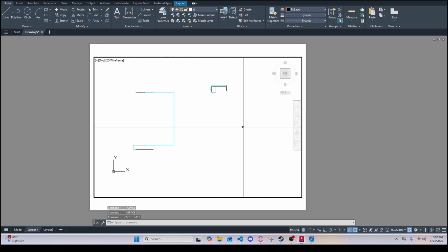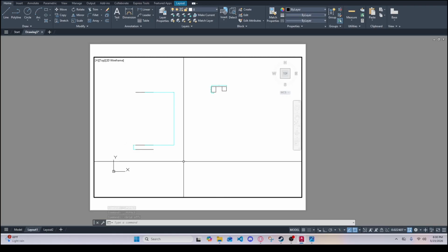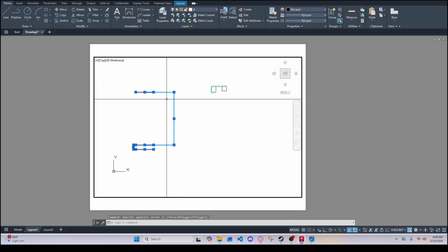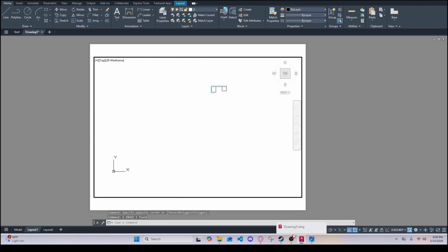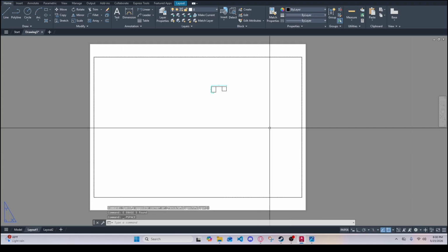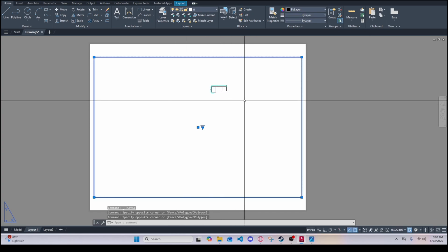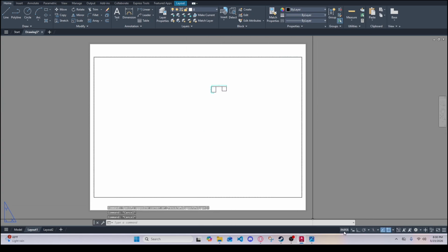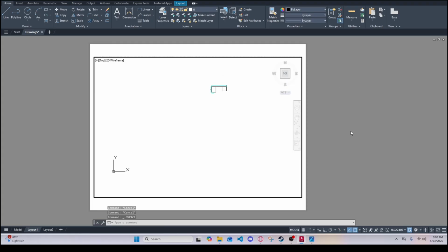Now this is where all this dimension line kind of matters. I'm going to go ahead and delete this, because you can also delete stuff from paper space, but remember, it's like you're still in model space as long as right here says model. Otherwise, you can't do anything here. As much as you highlight, it's only going to highlight the viewport, paper space. I can't do anything outside here, only inside.